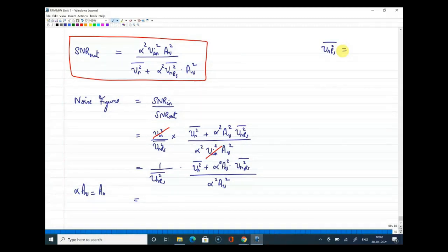It is the power spectral density we have written. I hope you remember it as 4 kT into Rs, or for any resistance R it is 4 kT into R. Pratap, it's not 3 kT, it is 4 kT into R, the voltage noise spectral density.